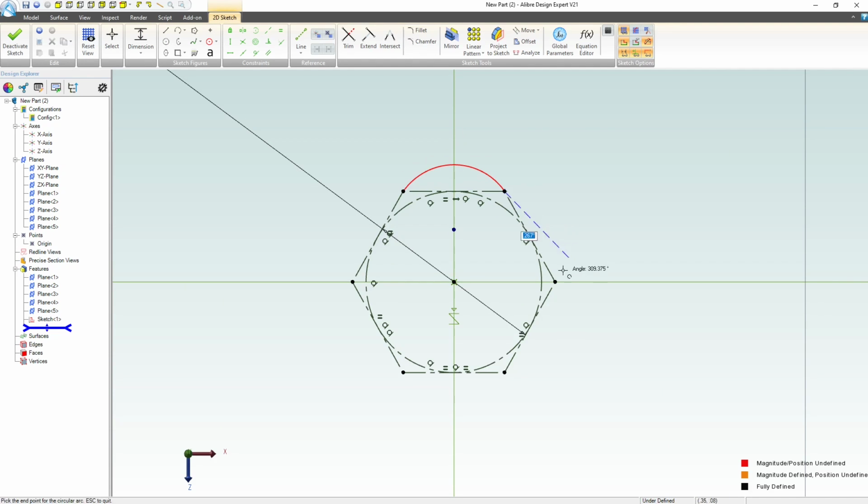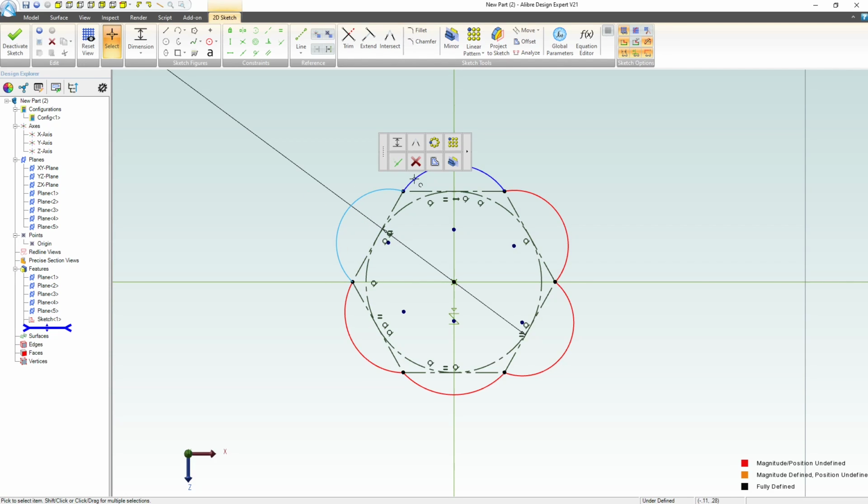Now you can also try to do an arc by its center point and run to 3 defined points, right? I have 3 defined points, and so you could get a fully constrained arc right off the bat. Every platform that I've tried that on, I've had some sort of difficulty, including SolidWorks. So I'm a little bit more cautious about that method, and if you're a control freak like I can be about constraints and relations, sometimes it's nice just to add them yourself.